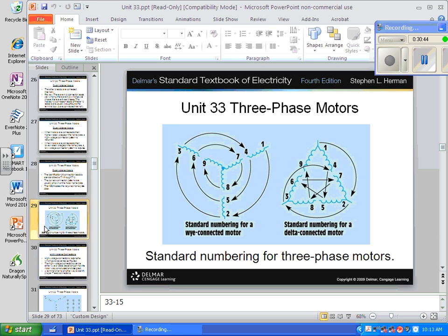And then in the lab project where we do this, we're going to find these pairs because they are paired, they're connected. So we know that it's either 1, 4, or 3, 6. We just know they're pairs at first, right? But we can energize these windings and find out which ones get activated and which ones don't. And that's in the lab project, and you learn a great deal from that. You really need to do that project.